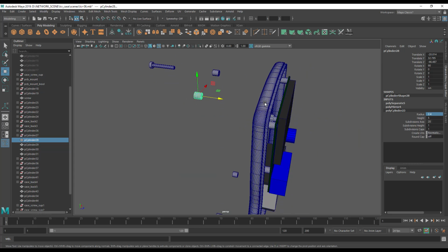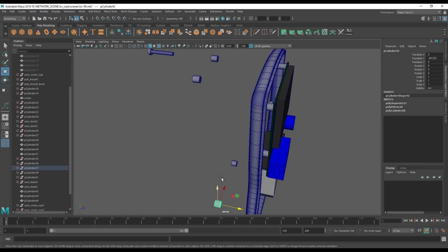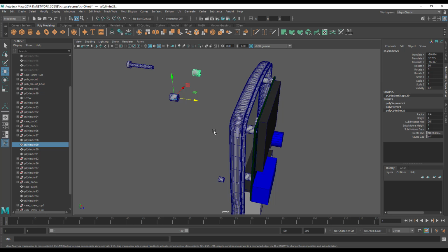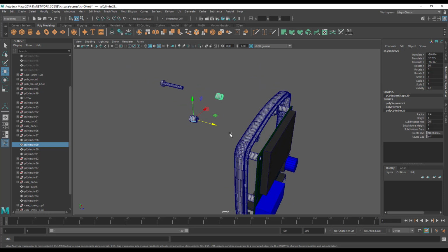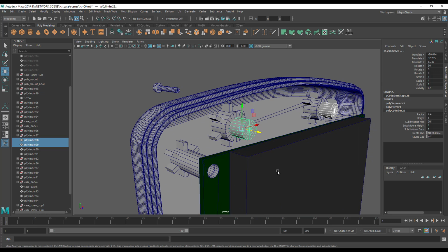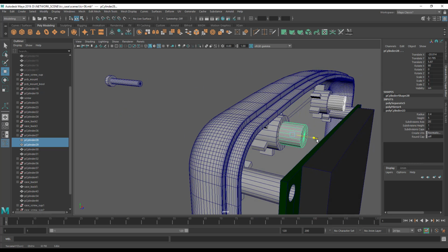Okay, so that should have sized those two. Did that size all of these? No, let's make this one 2.4 as well while we're at it, and this one should have also sized down to 2.4, 2.4 and 2.4. This will mean we can put a 1.4mm diameter hole through these, and they will have plenty of plastic either side to support that. So let's bring these out and just sit them on top of here.